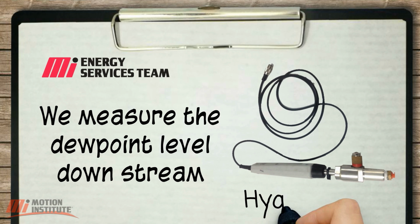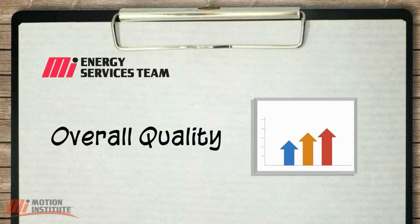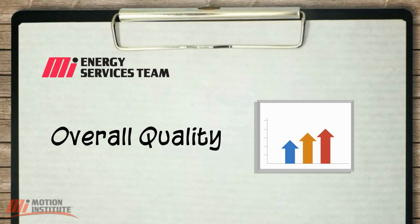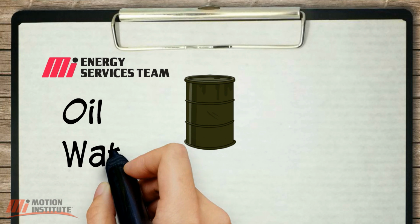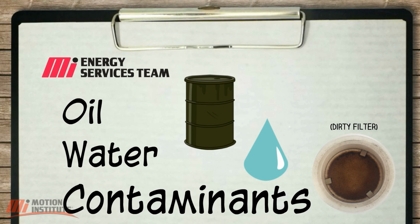Monitoring the dew point levels downstream of the operating dryers helps to determine whether or not the dryers are working to standard. The necessity for the overall quality of the compressed air varies from industry to industry. Regardless of the need for clean air in terms of the process, achieving the true life of a pneumatic component is extremely dependent on air purity. Passing oil, water, and contaminants downstream can have negative effects on almost any pneumatic component.